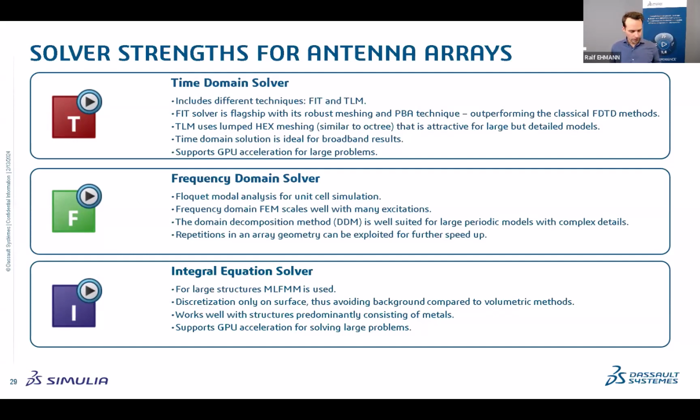Then there's also the integral equation solver, of course, for large structures, using MLFMM. It discretizes basically only the surface, so of course avoiding a lot of elements in the volume or in the background, and it works well for structures that are predominantly metals, although it supports dielectrics as well, and for acceleration GPU can be used.